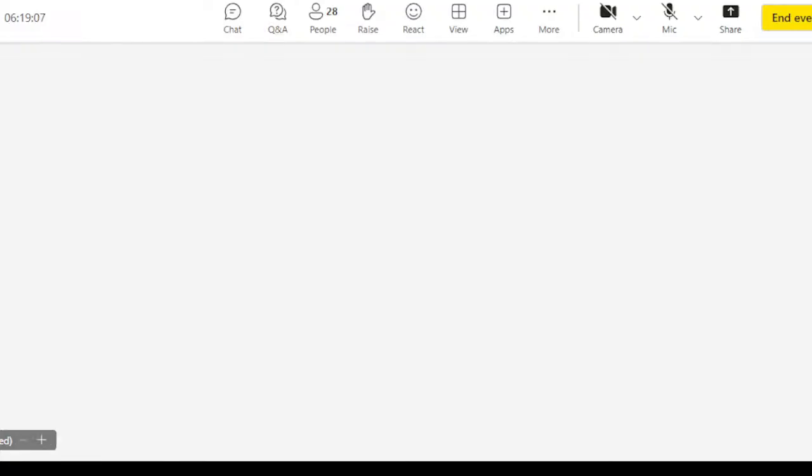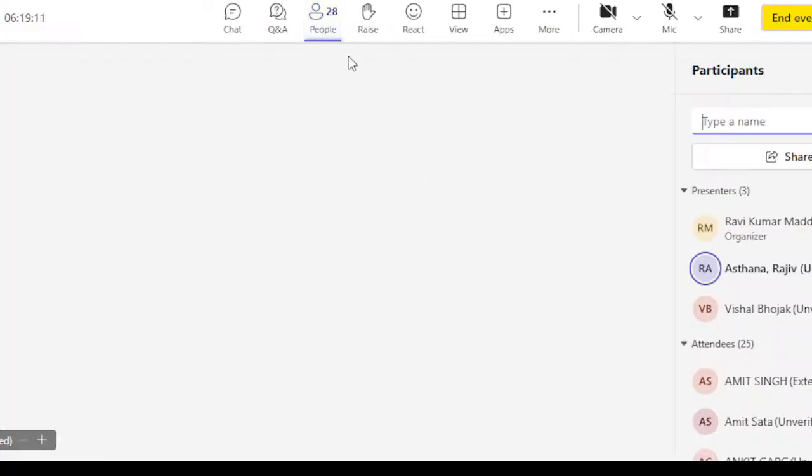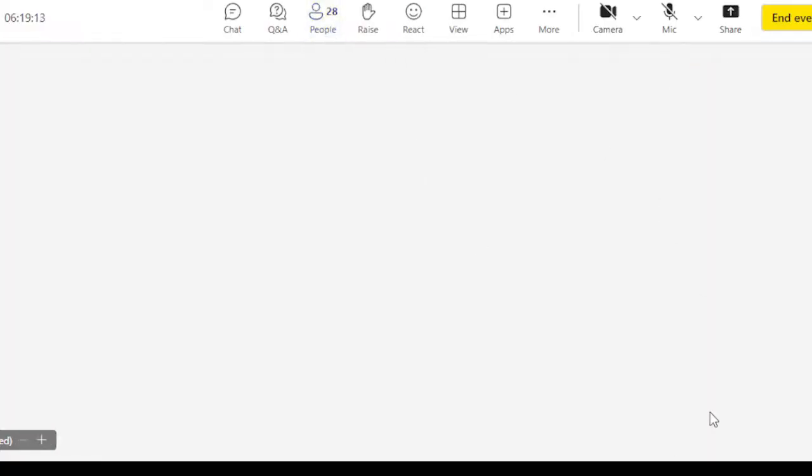And again, these are the properties of some fibers and matrix materials. We don't have to look at all the details, but let's see some general things here. Density: fibers are pretty light compared to metals, so there is no disadvantage in terms of weight. For example, nickel, steel, and superalloys are pretty high density.